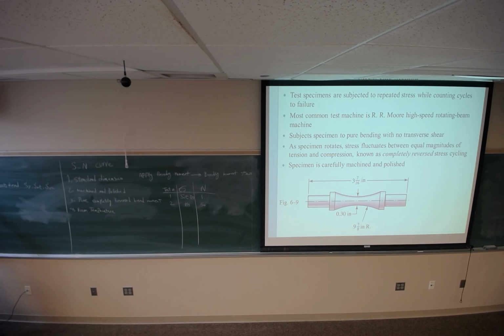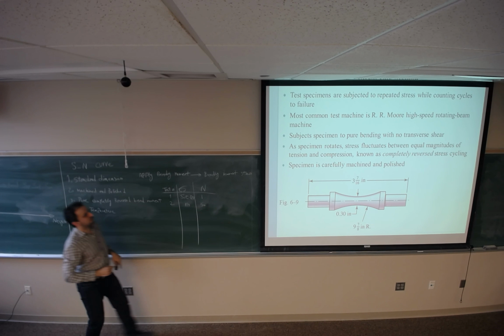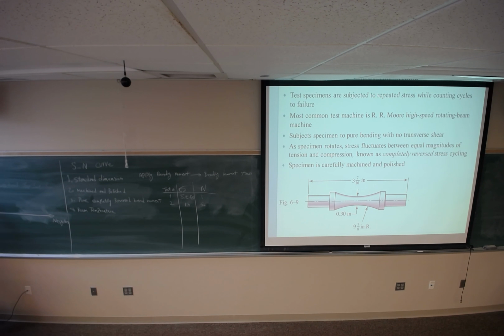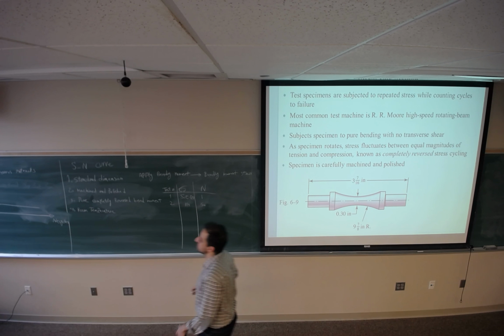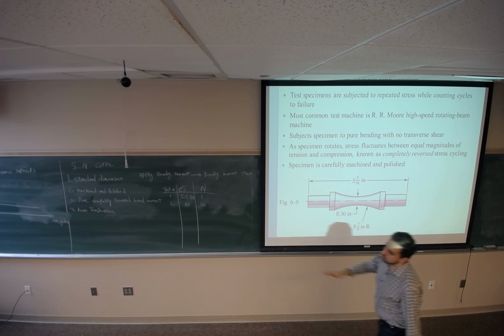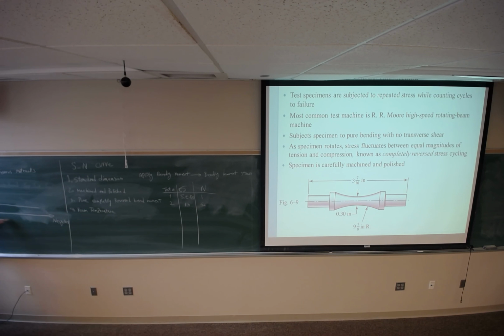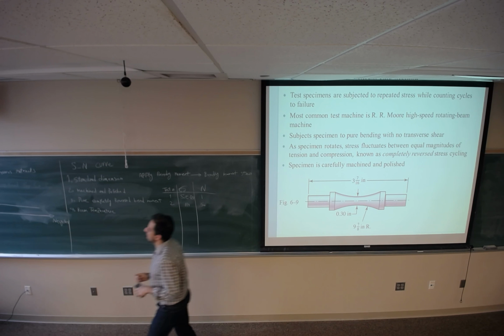Then on a curve, with N as the number of cycles and this as sigma, or we call it fatigue strength, just find this spot. If you do that for ferrous material, ferrous material would be the materials which have iron in them, you are going to get something like this. Number of cycles versus S_F is going to change like this.